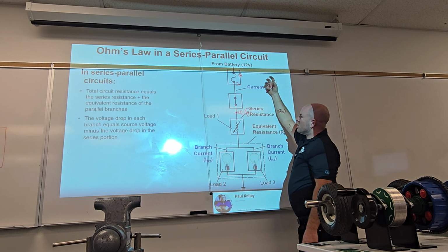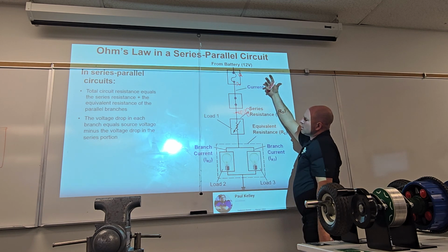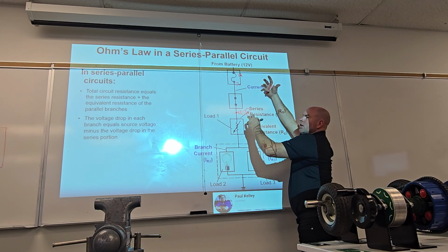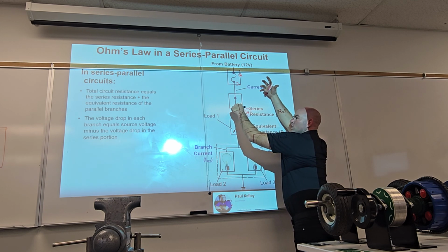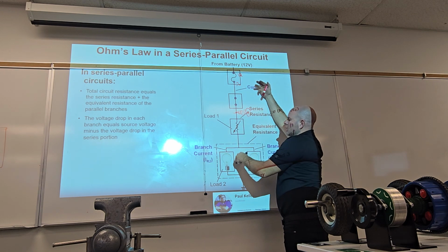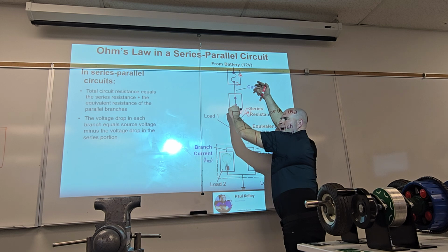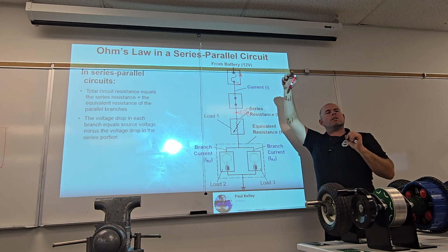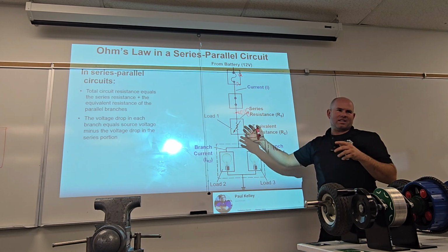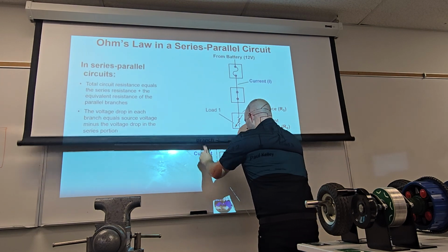If this bulb is glowing, and I disconnect down here and it's still glowing, then I disconnect here and it's still glowing, then I disconnect right here and it goes out, that tells me it's between here and here. Make sense? That's like the best way to find the short. You literally put the bulb in there and then just disconnect things until it goes out. And when it goes out, it was after that last thing you disconnected, but before the thing that didn't make it go out. Kind of, sort of. So that's a good way to do it.